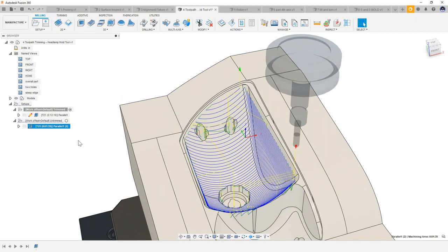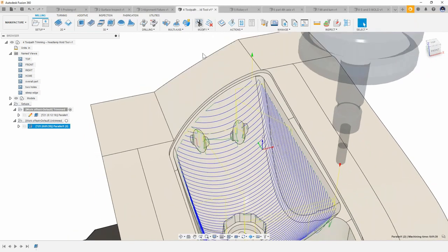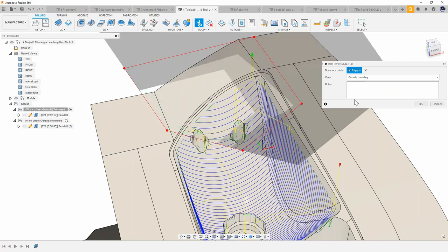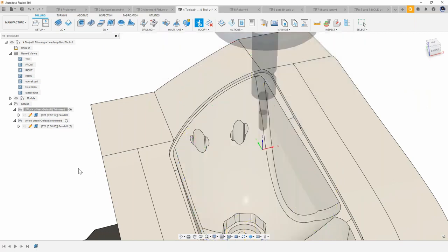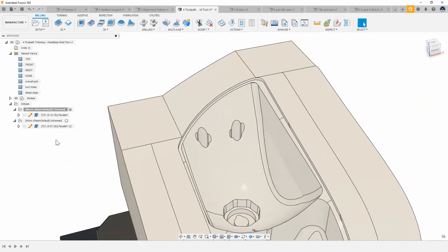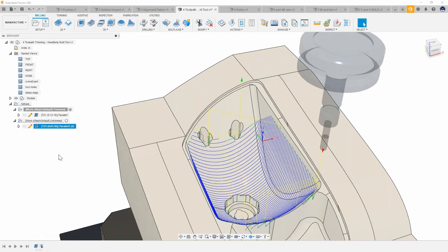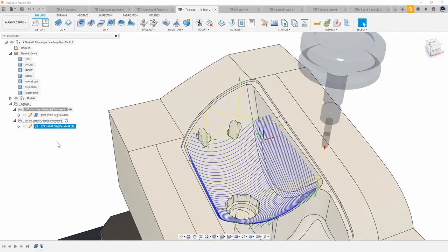One other thing that is new is I'm going to randomly make another one of these here. We'll just say that we'll trim off an area like that. I'm going to put a note in here, trim for MFG. And when I put in that note, this will let anybody else looking at the toolpath, when they see the edit and maybe why it was done, they can hover over this option and you can see there's a note there and it says trim for manufacturing, or MFG for short. So it does allow other operators to see maybe why something was trimmed off and whatnot.